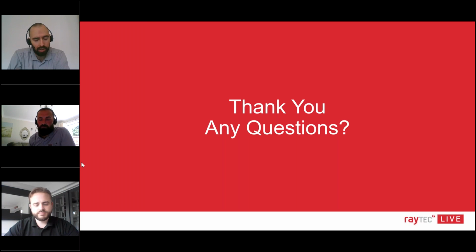Great, thanks both. I hope that answers your question, Marcel. The next one is more of a comment really from David. EX inspections required every 3 years, I believe. Reduced maintenance of EXE is a big advantage. That's certainly something that we would agree with. Any other comments on that? Yeah, just as we've covered. As we've talked about, EX inspections are required every 3 years, and if you've got an EXD fitting, it just takes you longer, it's more expensive, it's more difficult.